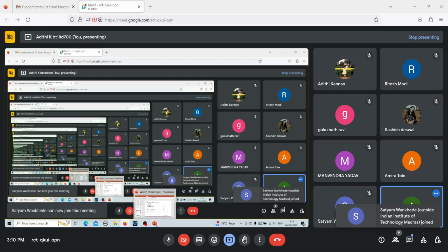If you have a very big ball, it will keep touching the walls of the cylinder, and that will also have an opposite direction force. You don't want that. You want your measurement to be strictly due to the fluid present in the cylinder and not because of the wall of the cylinder. Which is why when you select a ball, you select one with a very small diameter. That is one of the main constraints in this method of viscosity measurement, where your balls will be of known density and small enough so that they are not dragged by the walls of the cylinder. This is known as the wall effect.